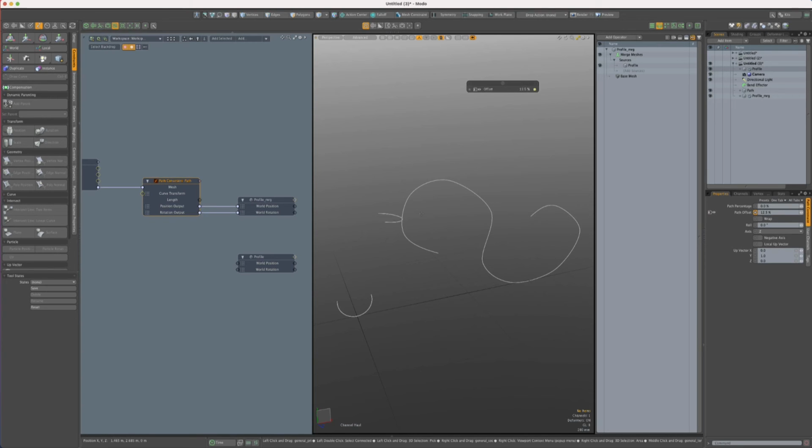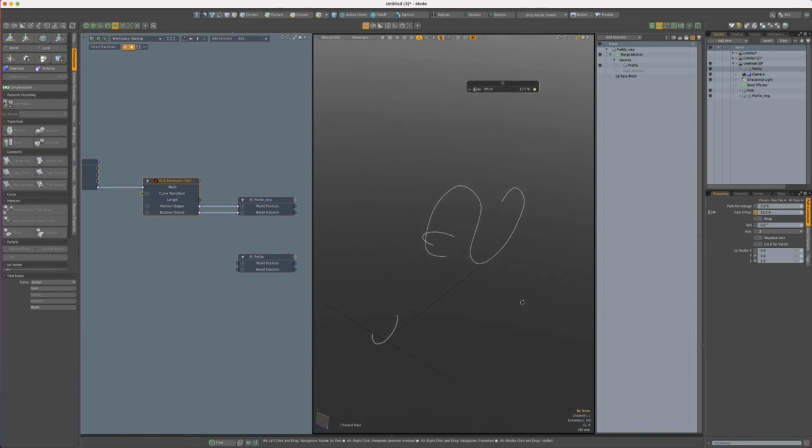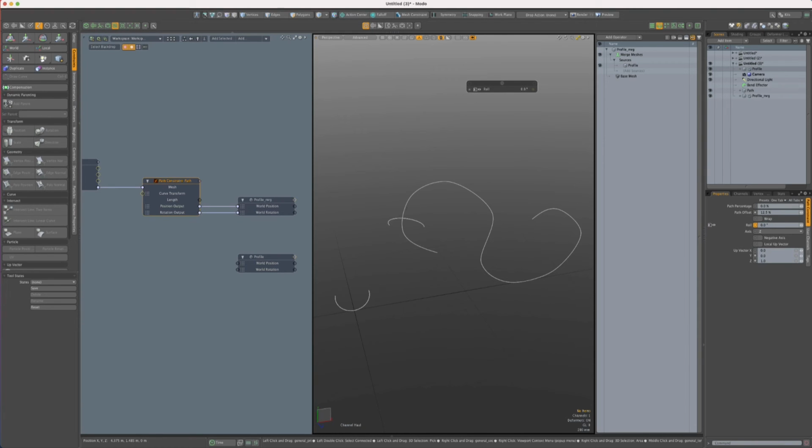And so we're just going to use a different axis. So I'm going to use the z-axis. So I'm going to change this value to 0. I'll change this to 1. And now you can see it's pointing down the z-axis. And we can just roll this back into place. So I'll put -90. So keep that in mind. You might have to change your up vector depending on how your curve is oriented, but you have some good controls here. There are more complex ways that you can assign an up vector to like a separate object, for example, but we're not going to be getting into that.